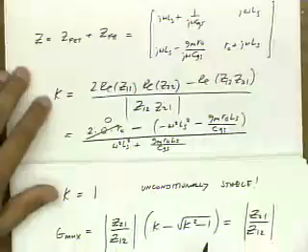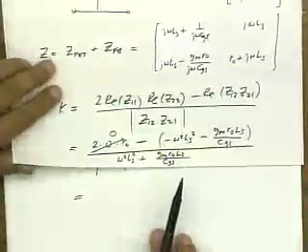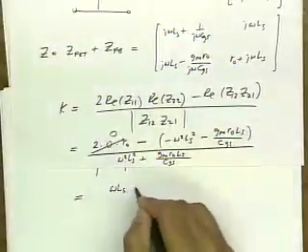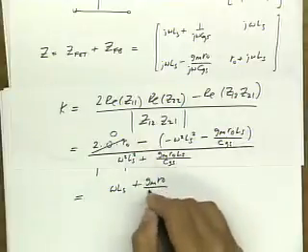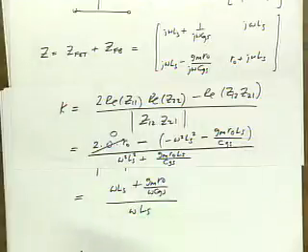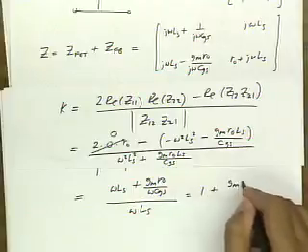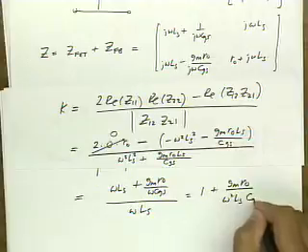And Z21 we found, this is Z21 magnitude, and this is Z12. So if I just substitute here, sorry I can't show both. Maybe I can try. So Z21 magnitude is omega Ls plus gm ro over omega Cgs, over omega Ls. And if I simplify this, this turns out to be 1 plus gm ro divided by omega squared Ls Cgs.